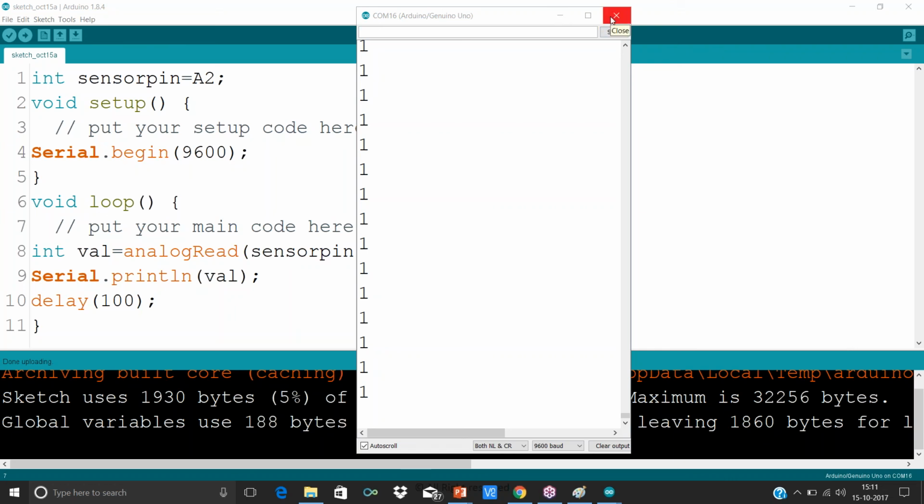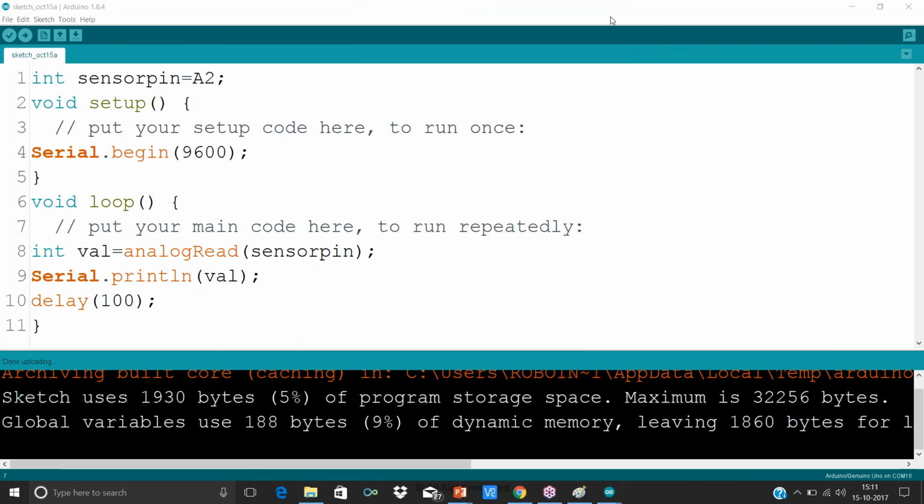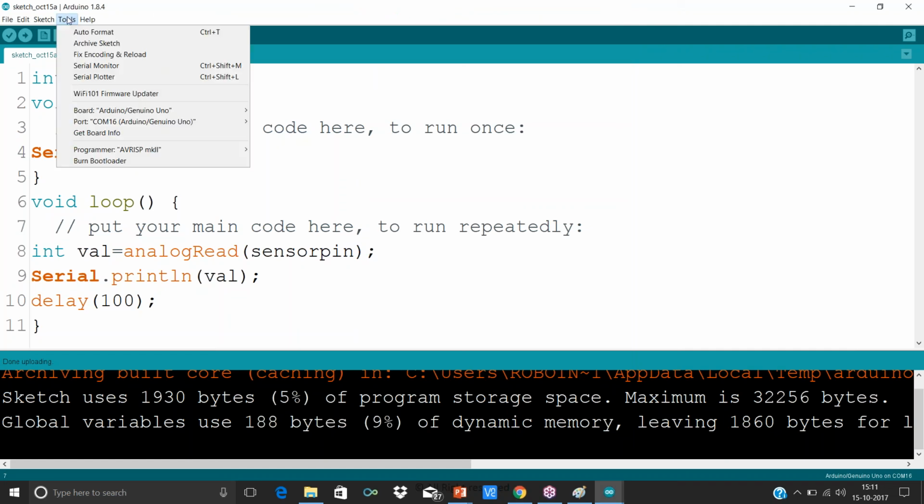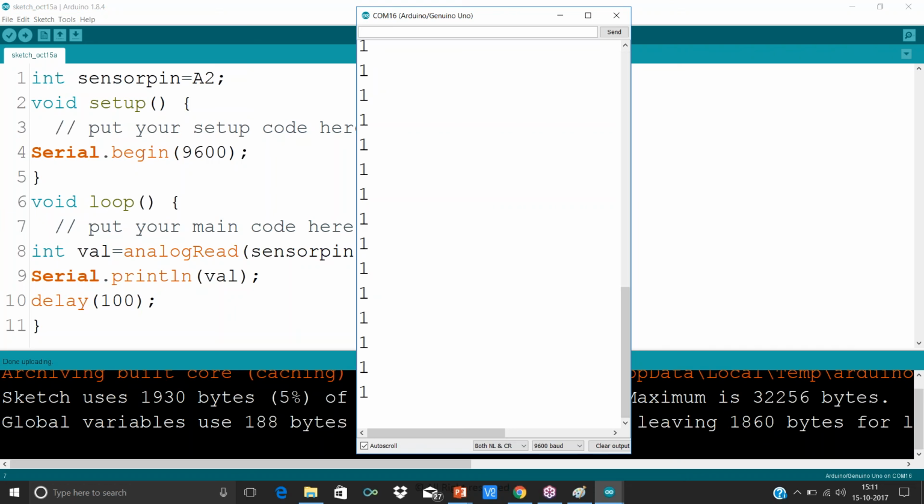Meanwhile, everyone, we can also do graphical analysis of this. So how do you do the graphical analysis part? You can see the values. Can you analyze the different values, the higher values whenever there is an object, and lower values whenever there is no object? Put your hand in front of the sensor and the values will be higher. Like you see, if I put my hand in front of the sensor, I'm getting 700 something, and remove hand, lower values. I hope you're able to observe the difference, right?